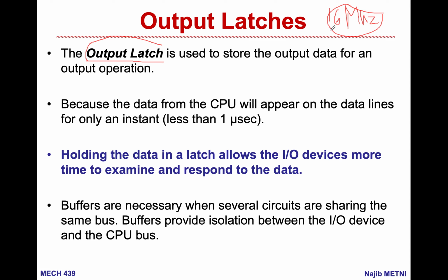So it will not anymore have a 16 megahertz frequency, so this one will not be present only for 1 over 16 microsecond. It will be present for a time where at the end I will change it by writing again a low on the pin. So holding the data in a latch allows the input-output devices more time to examine and respond to the data. This is why, because the outside world, being a motor, being a heater, being an LED, needs time to respond to data. So I need this data to be latched.